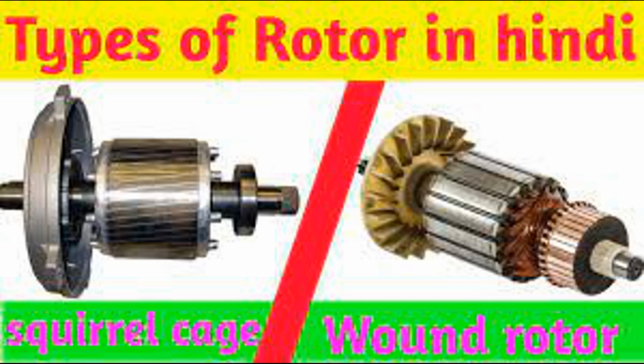During the positive half-cycle of the AC waveform, 2 of the diodes conduct, allowing current to flow in one direction. During the negative half-cycle, the other 2 diodes conduct, allowing current to flow in the opposite direction. This results in a series of positive and negative pulses. Filtering. The pulsating DC output still contains ripples or fluctuations.